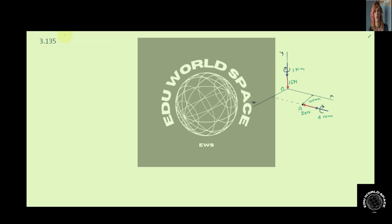So first of all, we will try to find out the equivalent force that is acting on this system. The equivalent force, let's say R, can be found by adding the total forces that are acting here. This 15 Newton is in the negative y direction, so this will be minus 15 j cap, and 20 Newton is along the negative x-axis, so it will be minus 20 i cap.